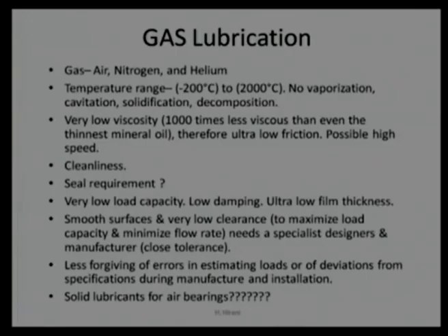That means we require very good smoothness of the tribo surfaces. Now, this is imposing a major design problem. The surfaces need to be very smooth, and by the way, if they come in contact, there will be very high adhesion.